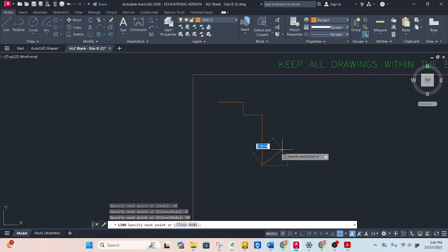And this is where it gets a little confusing because I've got to go backwards. So we're going to go this way. Instead of 0, I'm going to actually use 180 degrees. It goes back 1.75, tab, 180, enter. I'll go straight up and connect there. And I've got this line that's following along. It thinks I want to draw more lines. I don't. So I just hit Escape, and there we go.